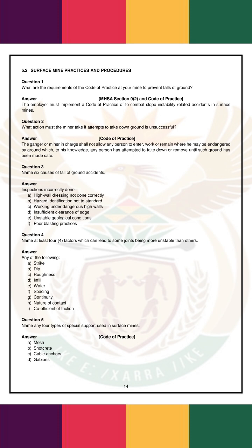Inspections incorrectly done. 1. High wall dressing not done correctly. 2. Hazard identification not to standard. 3. Working under dangerous high walls. 4. Insufficient clearance of edge. 5. Unstable geological conditions. 6. Poor blasting practices.